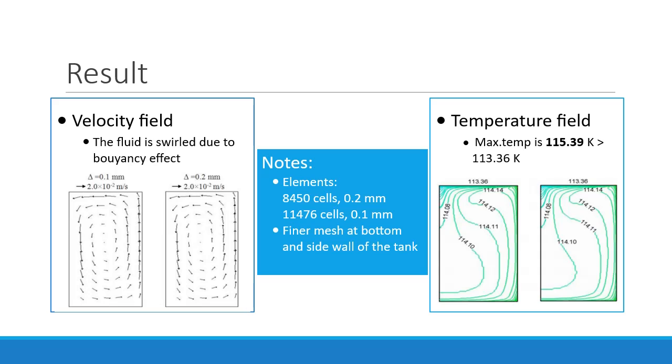Those are good mesh sizes. We could observe the heated fluid phenomenon by paying attention to the temperature profile and the change of direction of the fluid. It moves upward along the bottom and side walls because of the buoyancy force pulling the lighter fluid up. And then the fluid is cooled near the liquid-vapor interface and moves downward. The movement of the fluid creates a kind of vortex in a counterclockwise direction.